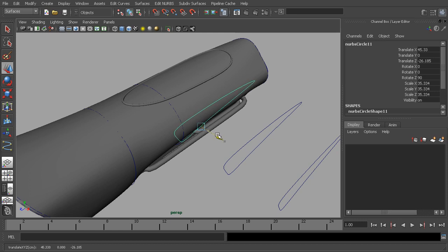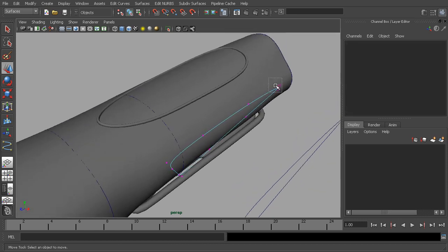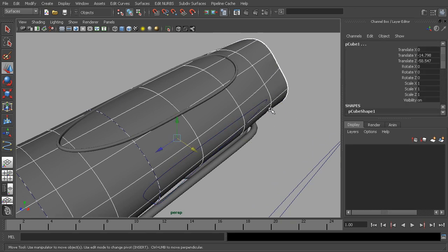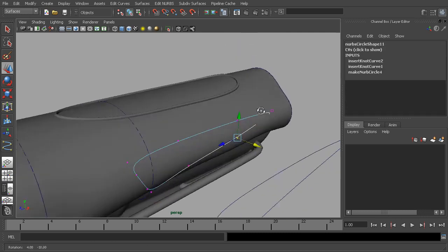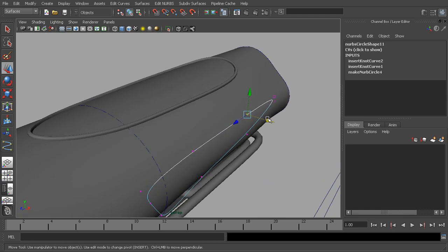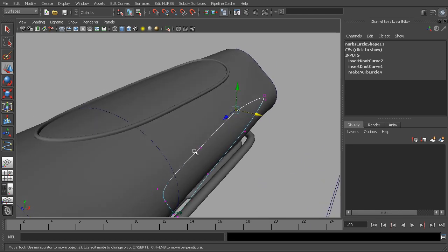And then rather than projecting down, I'm just going to manually take these points and move them towards the surface until that curve is right on top of that plane. So kind of moving it in and just moving it in one axis only.